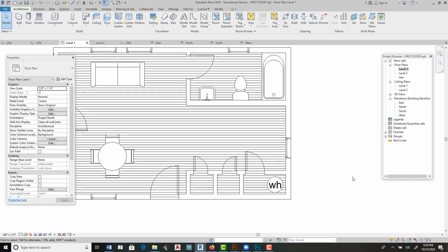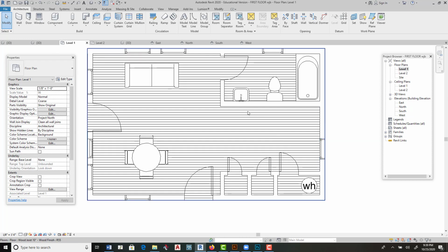Once you get those walls in order, you're going to start looking at the cabinetry. Cabinets are 36 inches high, 30 inches in the bathroom for children. The adults are usually in the kitchen, and you have a countertop. The countertop is 25 inches with a 1 inch overhang lip. So the cabinets are 36 inches tall and 24 inches deep. And they have a backsplash about 4 inches by 3/4. So that's what we're going to draw today.